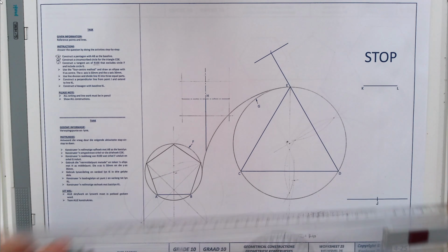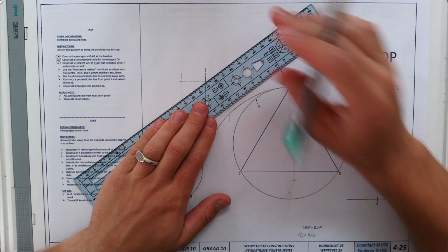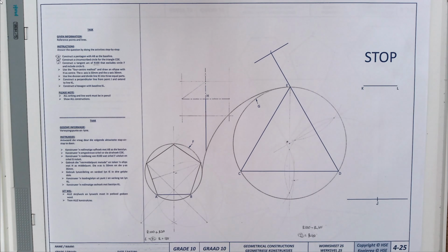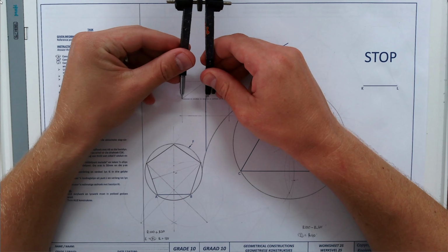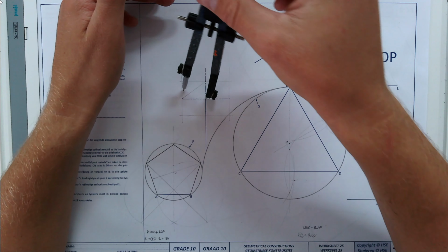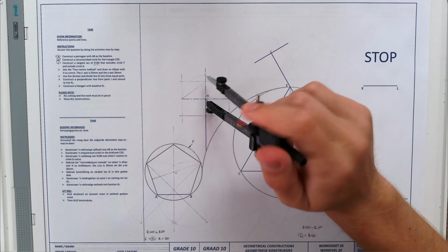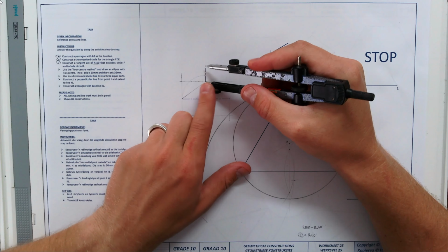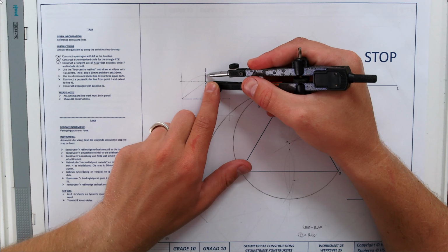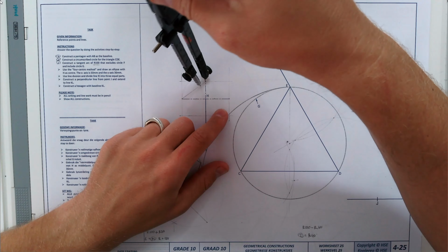Now we can start with our ellipse construction process. I'm going to divide this top left block diagonal from there to there. Then we're going to use our compass. I'm going to put the sharp point at H. We're going to take the lead to the border. We're going to draw a light arc all the way until we get to the vertical center line. From the border to that mark over there, whatever is outside of the border, this dimension we need to bring back to our diagonal line. So that dimension we're going to bring back to this line.